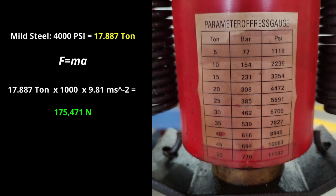The mild steel sample had a compressive load applied to it of 4,000 psi, as seen on the pressure gauge. We can convert this value to tons by using the chart attached. 1 metric ton is equivalent to 1,000 kilograms. We can use the equation force equals mass times acceleration to convert the mass to a force as shown.